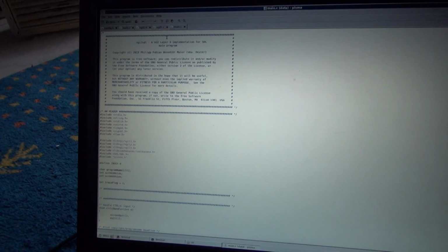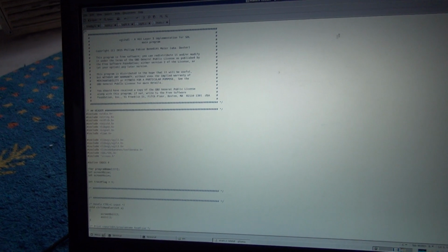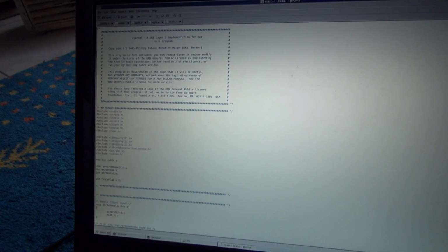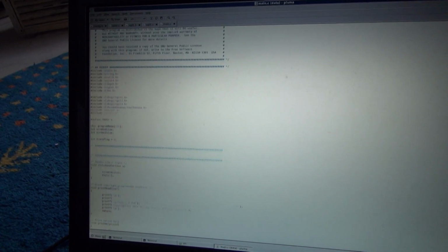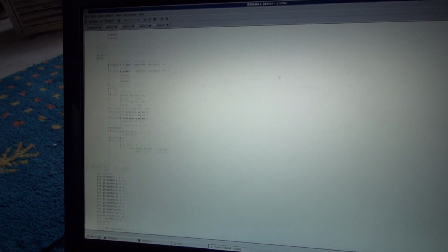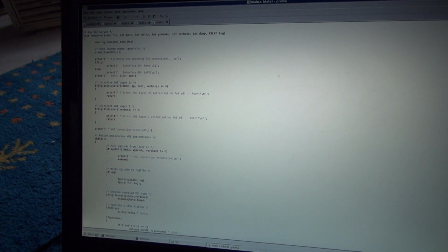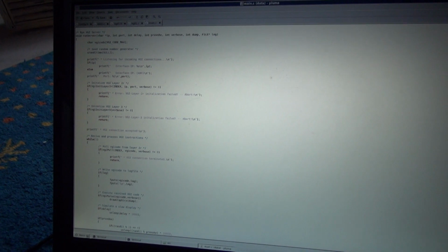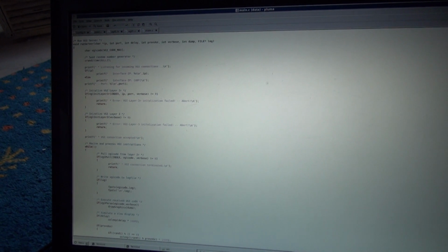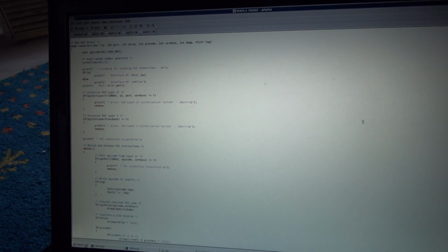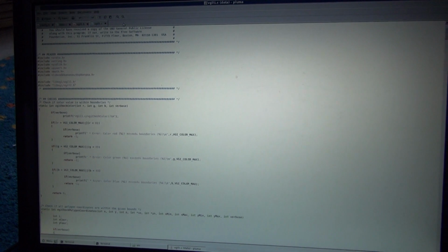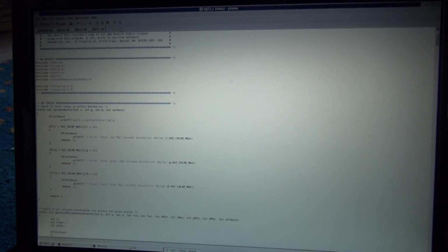When you want to implement your own hardware and use it with VGI, let's say you already have some vector output stuff, you could use this code as a starting point, and it's really just this. It registers a callback, so it uses the VGI with the callback. The VGI does all the rendering for you. As long as you know how to draw lines on your vector display, you are fine. So you can immediately start using VGI with your own hardware. It doesn't necessarily have to be the EasyLase USB.